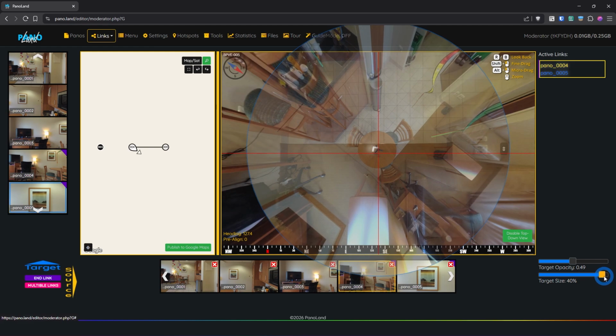Use the mouse to drag, hold Shift key for fine control, and Alt key for very precise adjustments. Look for a horizontal or vertical reference, like a floor line or ceiling edge, and line the source panorama up with the viewer guides. Then drag the target panorama to match the source.